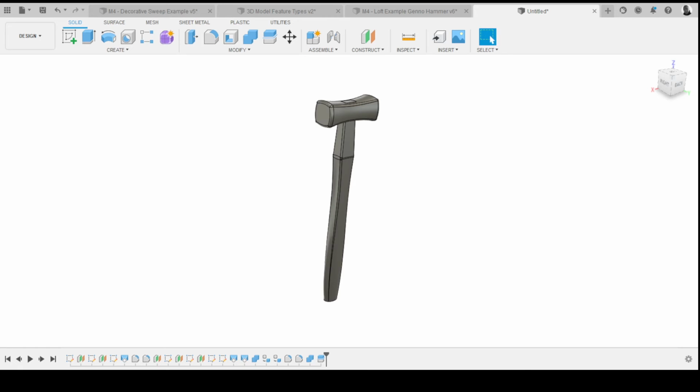When you scan something, it creates point cloud data. It picks up lots of points around the scanned object, and then the scan software will join those dots up in a 3D dot to dot and create lots of triangles. And it's a completely different modelling operation to what we do here. So then you have to convert it basically to parasolid modelling, which you can do within Fusion. It's recently put in some really handy mesh tools where you convert mesh into parasolid models. So, long-winded way of saying yes, you can do that. But if it's more for engineering parts, you're probably going to want to actually rebuild a CAD model from scratch rather than use scan data.